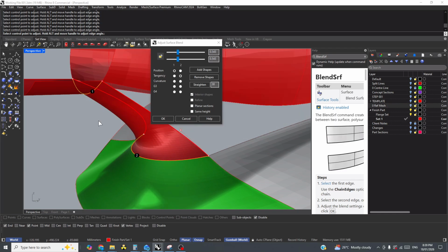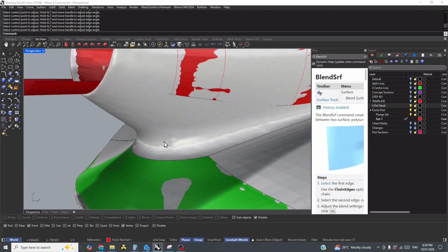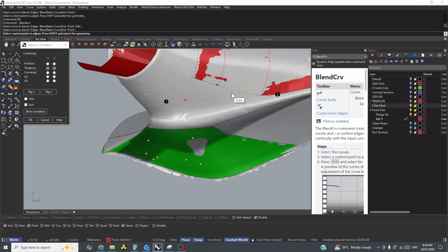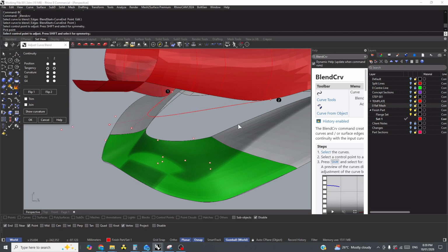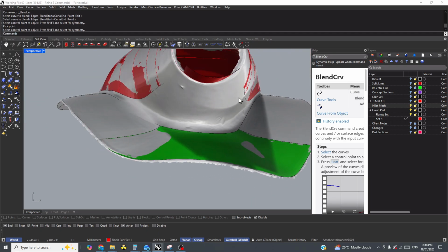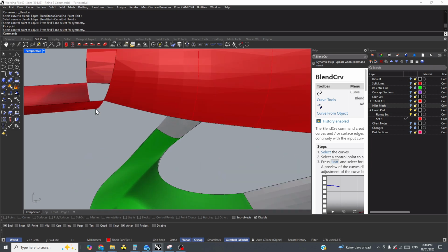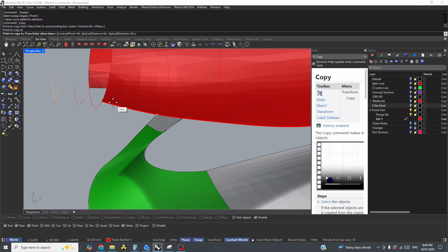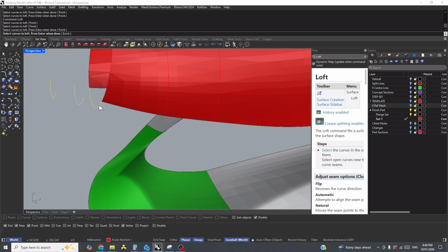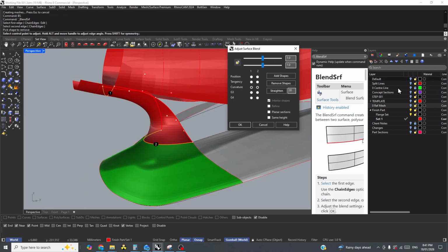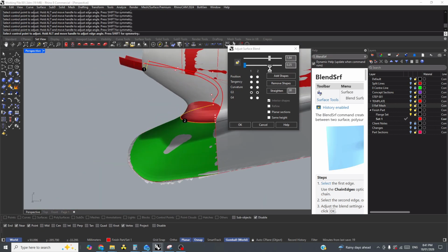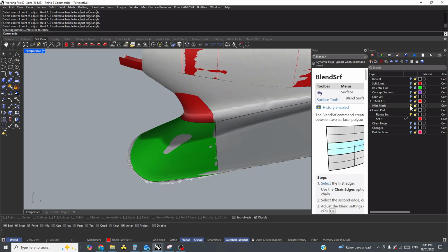The other great thing about this is, say you've got a point curve directly sectioned from a scan and it has like 500 points on it. Do not simplify is going to take a while to compute. So with this kind of presetting loft to rebuild, it saves you compute time on a big job, saves you waiting time, minutes, which when you're iterating quite fast to find shapes, can add up to a lot.